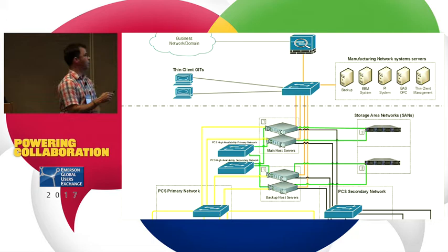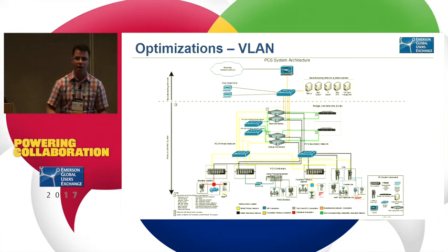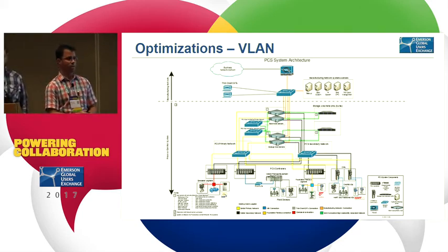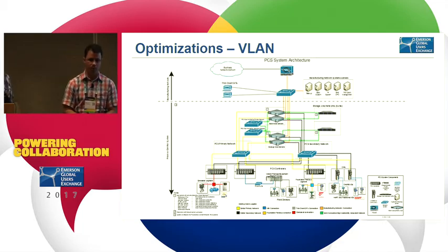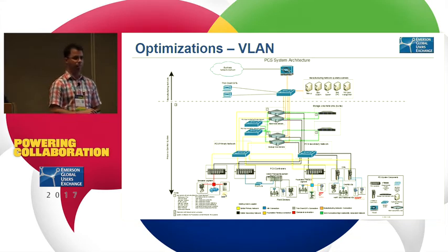So there's a dedicated VLAN for thin client OIT connection. So instead of having, as George mentioned, 125 workstations connected to the primary and secondary network of the DeltaV system, created in our database, we chose to have thin clients connecting from outside the DeltaV system using the manufacturing network and having a specific VLAN.